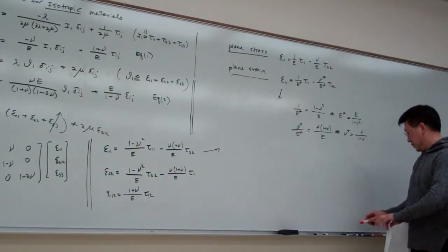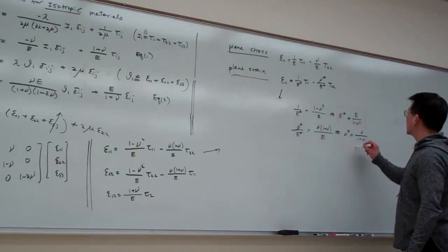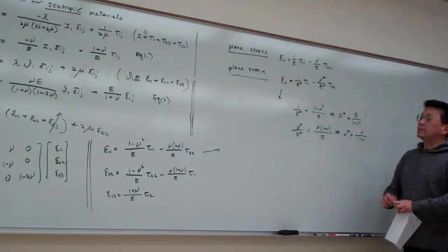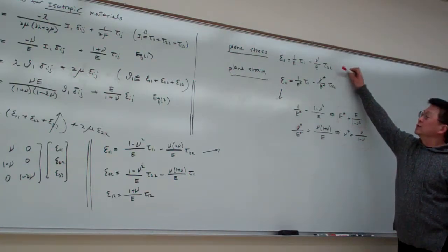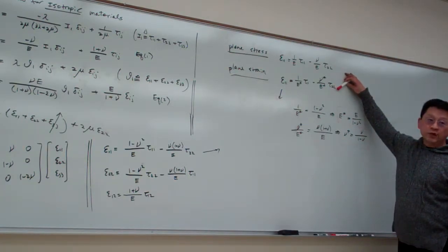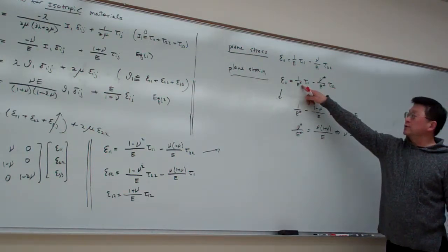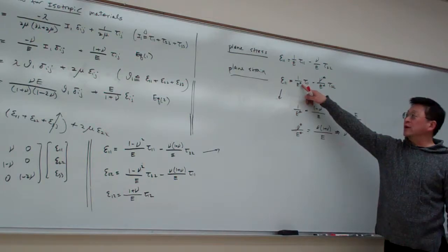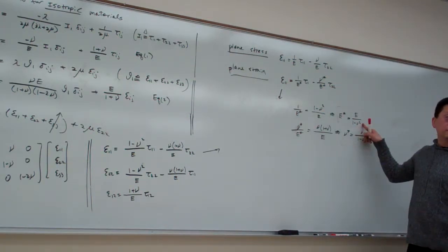This tells us a good property, such that we can utilize the plane stress as a template to write down the plane strain equations. As long as in the plane strain equations you replace the corresponding Young's modulus by this number. Got it?